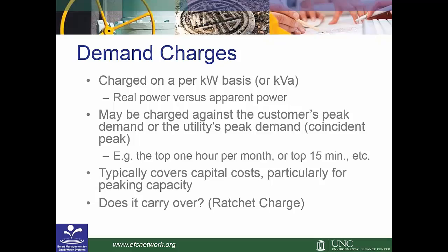With the demand charges, some of these rate structures will have what are sometimes called ratchets. They go by other names too, demand ratchets, where basically they look back when they're generating your bill each month and say, we're going to look at not just the top hour for this month, but the top hour for any month in the last 6 months or the last 12 months. And that highest peak across that whole look-back period is what we're going to charge you